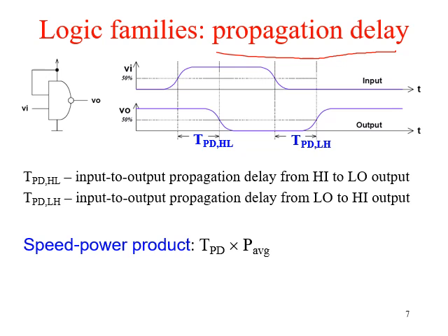Let us take the example of this waveform. Here Vi is denoting the input and V0 is denoting the output. This is working as a NOT gate, so 1 will become 0 and 0 will become 1. This is our input. We can see initially the input is 0 and it slowly rises to a value of 1, and then again falls back to a value of 0. And V0 will be inverted from Vi because it is acting as a NOT gate here. Initially it is 1. It takes some time to fall to 0, and then again it takes some time to rise to 1.